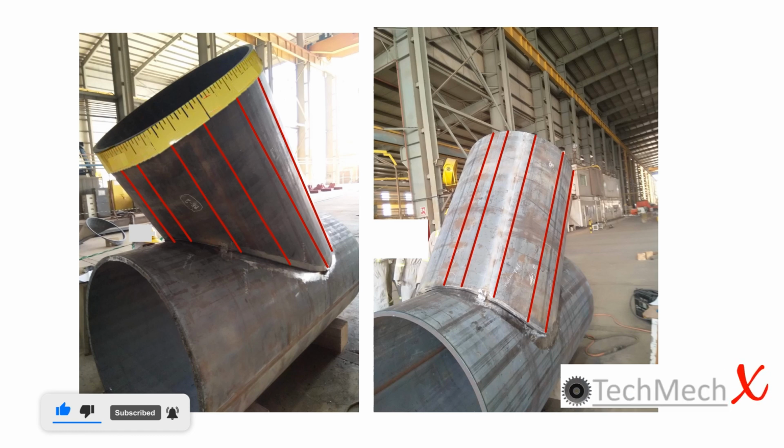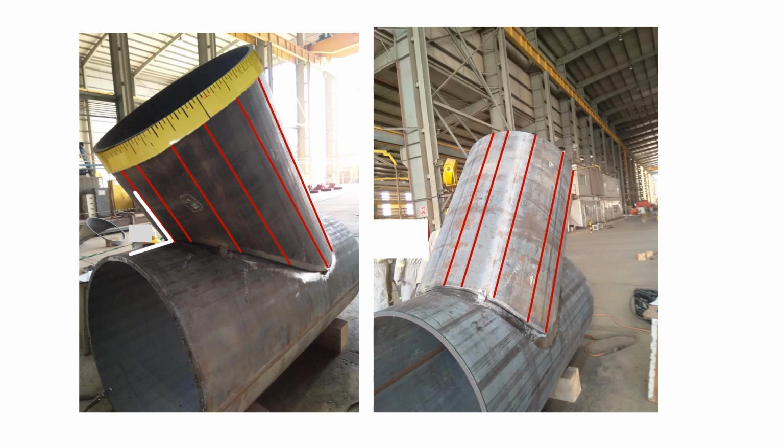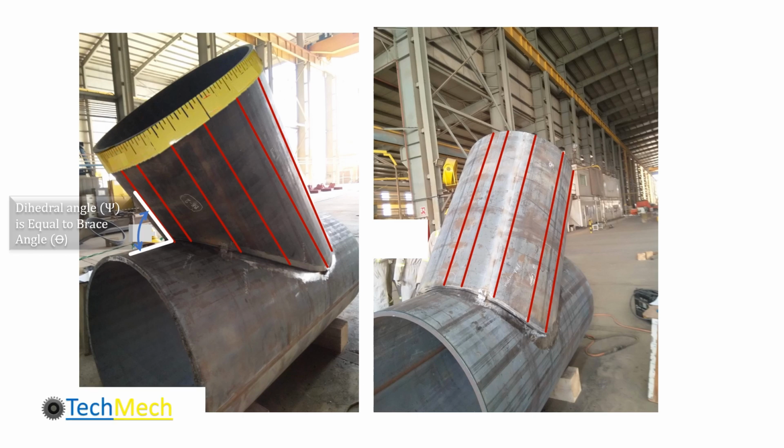Extend the divided parts line to the line of the weld. Remember, the center line at the heel area will be considered as the initiation point of marking. At the heel area, the brace angle is equal to the dihedral angle. So assuming the brace angle is 30 degrees, this area will be in zone 4 and the required weld size will be 1.75 times the brace stub thickness. Draw a perpendicular on the line of the weld using a right angle set square.